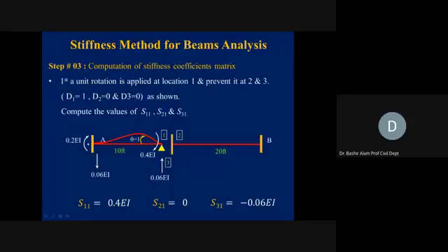At the far end, it will be in the same direction, so clockwise, and 0.4 divided by 2 is 0.2. Balancing couple will be 0.4 plus 0.2, 0.6 divided by 20, so 0.06. That easily these member end actions are generated. On the right-hand side, we have a fixed support. We don't have any rotation or settlement condition. No actions will be generated, so everything is equal to 0.